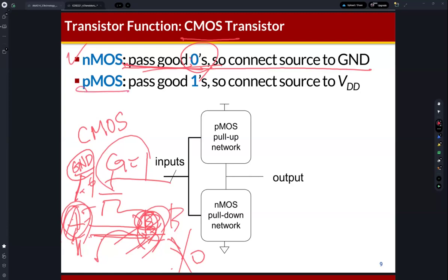The behavior of the PMOS transistor is the opposite of the NMOS transistor. We can use the PMOS transistor like a switch, right? But the PMOS transistor passes 1 well. When the PMOS transistor is turned on, if A is at high voltage, this high voltage can be delivered to the other node B, clearly. But if A is the low voltage, the ground level, then B cannot become ground level, clearly.